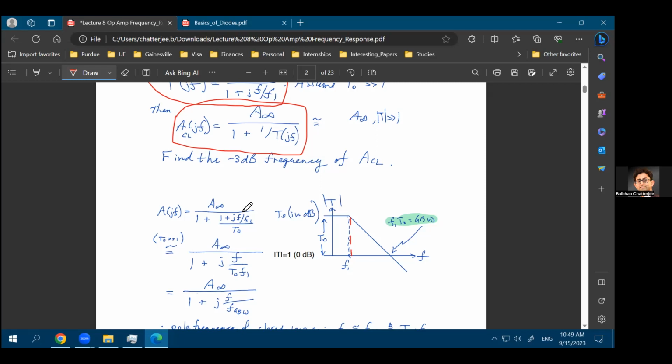Let's say you connect a 1 microvolt input in an ideal op amp, and you have a gain of, let's say, 1000. So you get a 1 millivolt output. So it can still be a circuit, but there is no feedback loop. The meaning of loop is that you have a feedback, right? That's the meaning of having a loop, that you have something coming from your output to input, and only then you can create a loop.